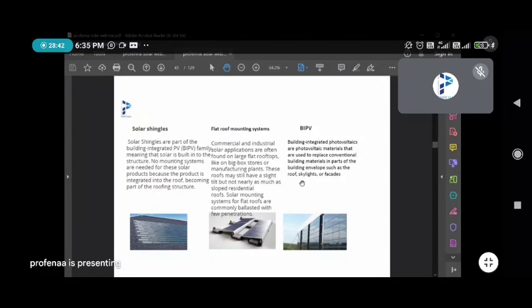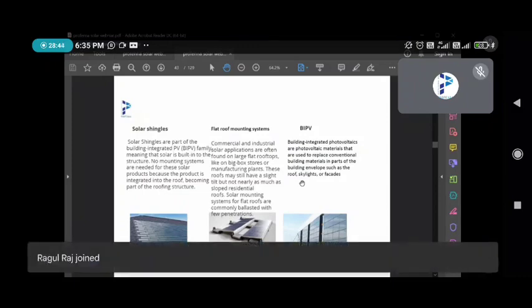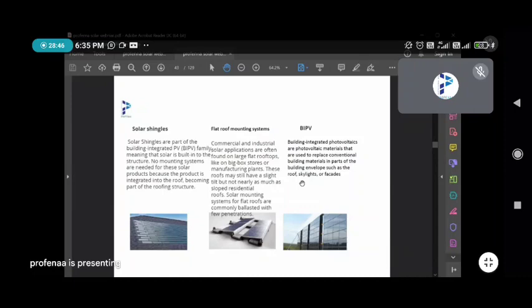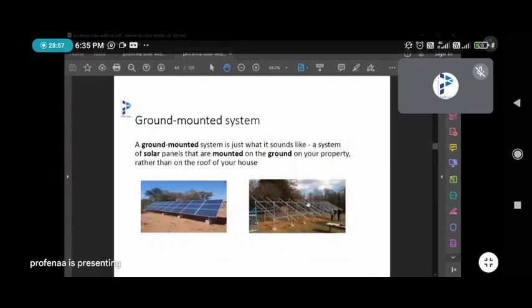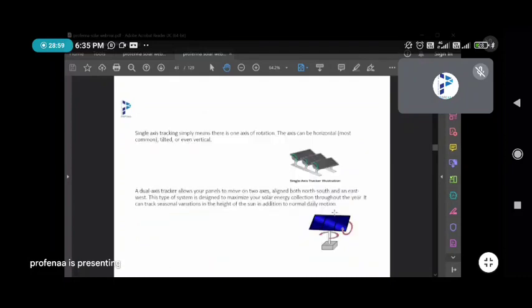So mainly they ask about structure. One question is which material they are going to use: either aluminium, cast iron, SS or galvanized. They also calculate wind speed, 150 or 190, and based on that the structure is selected. This is a ground mounting structure, sir. This is the tracker which I have used. Based on that, you will get the generation.